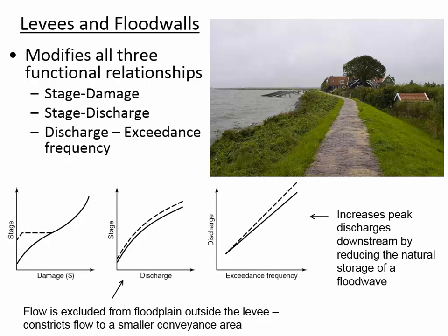So let's draw a little diagram here. Before the levee, maybe it was like this. The water would flow like that. But they say, well, we want to build around here, so instead of having the water there, let's put in a big levee like that, and this is exaggerating things, obviously. If we put in the levee, then the water level will be here, and then we can put in crops down here, or we can build a house there. Now more of the flow area is far away from this frictional surface, and so it's increasing the flow rate.